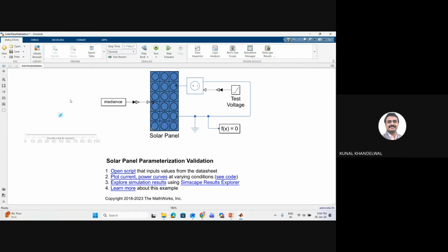Yes, basically that is what exactly we want to do. We want to minimize the thing, and the most important thing is we should use the manufacturer datasheet here itself. Normally we have to see temperature between 25 to 50, depending on the manufacturer and where exactly we are going to place the solar cells. From manufacturer to manufacturer, it will be different. Basically, we should focus more on the number of cells in series and parallel. Thank you. Thank you, sir.